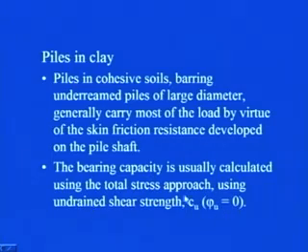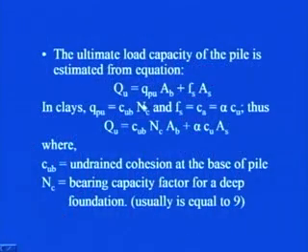So, we have to use this total stress approach. The ultimate load capacity of the pile is estimated from the equation. In a similar manner, the general equation is Qu is equal to Qpu, which is acting over the area Ab, the area of the base of the pile, plus Fs into As. In case of clays, Qpu is equal to Cub into Nc, that we have already discussed,